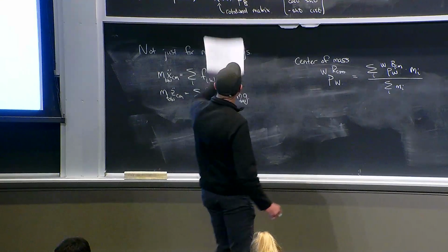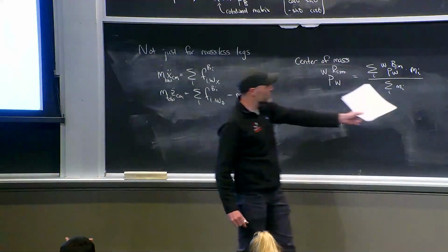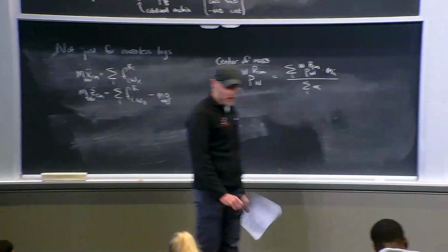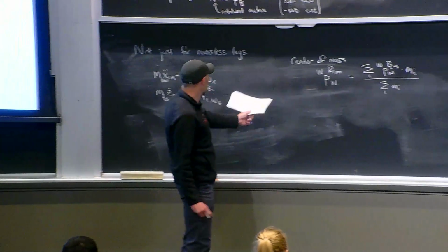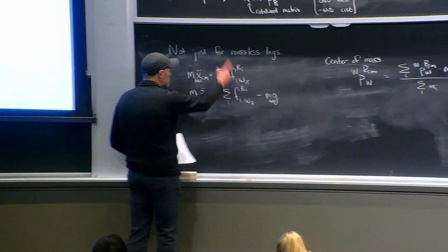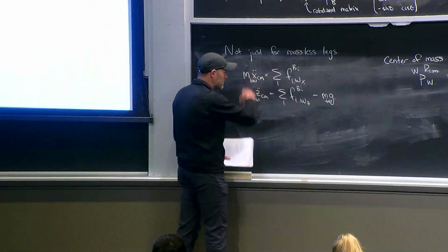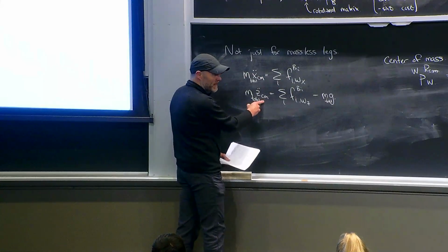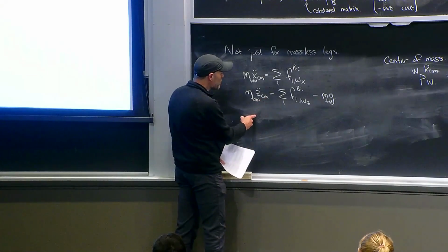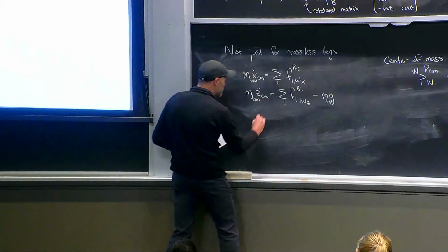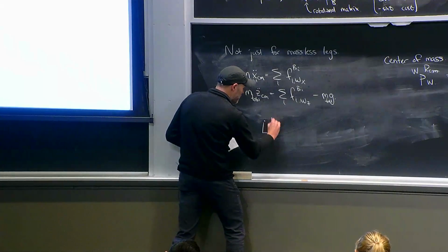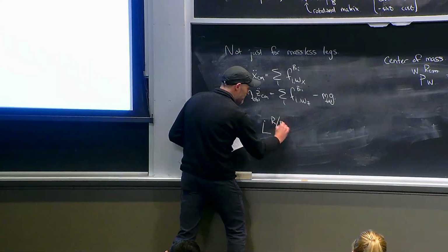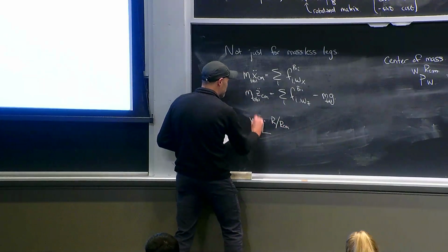Okay, so if you think of these dynamics as simplifying to the spatial momentum equations, then what is the natural generalization for the full humanoid? We're going to control its center of mass, and we're going to control the angular momentum. What we really want is that these equations are the L dot of the entire robot relative to the robot's center of mass, expressed in some frame.